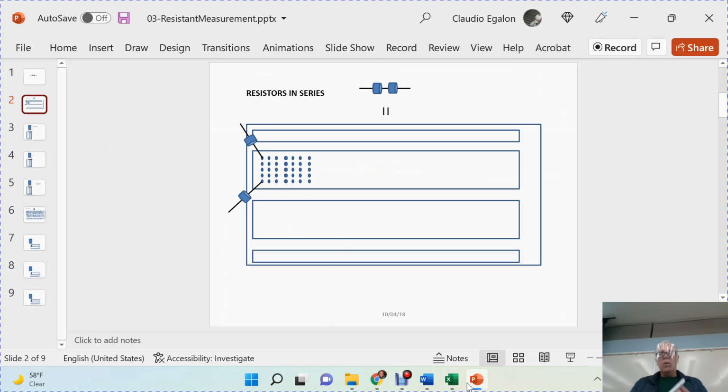You go ahead, plug one resistor into one of the holes, any of those, in the vertical, and plug the other one in this vertical line. Don't put it here, don't put it here. It has to be in this vertical line. This proto board was built in such a way that we have a wire connecting those holes in this direction, another wire connecting these holes in this direction, and so on.